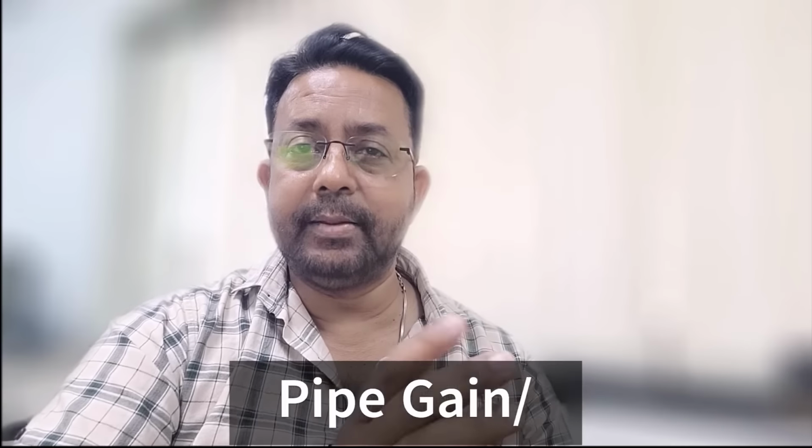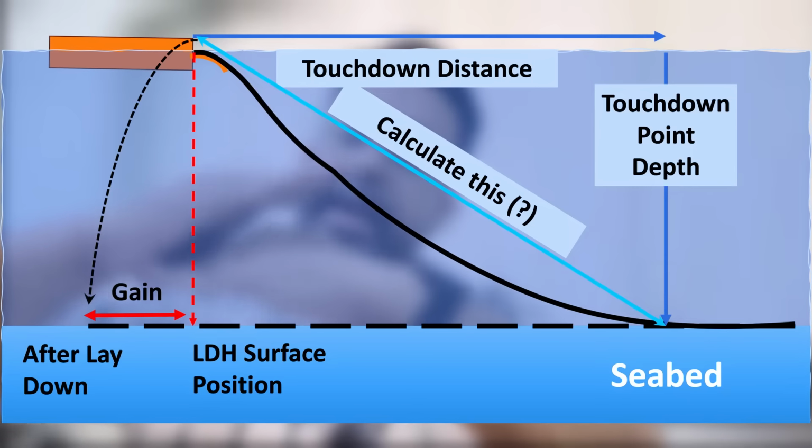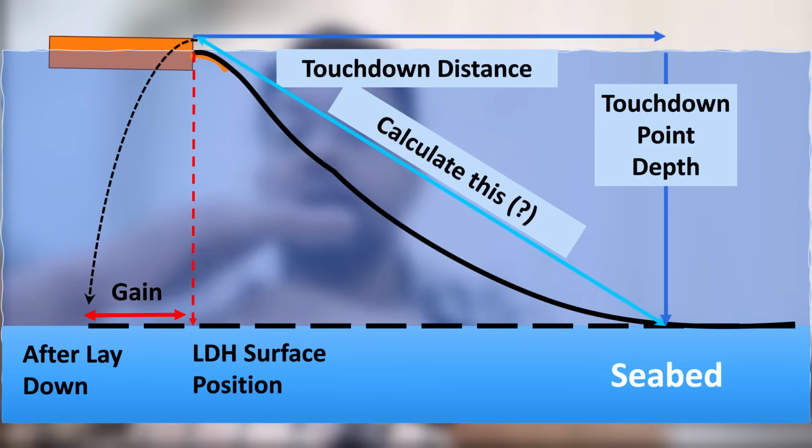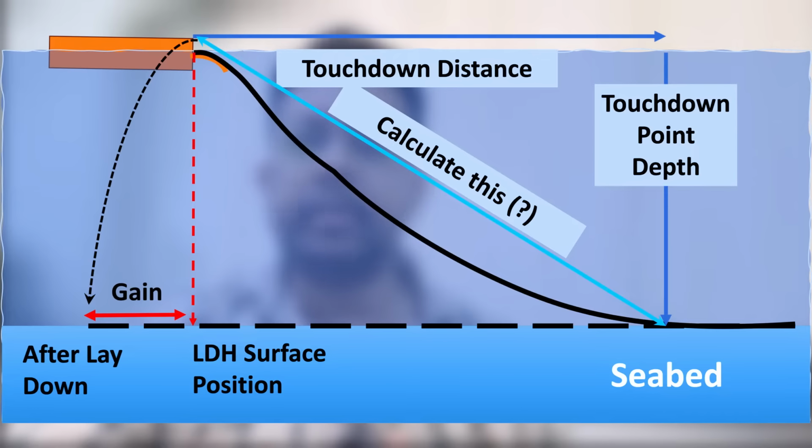Here you need one more data from the field engineer, and that is gain or flop forward. See, the end of the pipeline is on the barge, which is say about 80 meters above the seabed. So when it falls down, it gains a few meters from the position calculated at the beach stall. You can do a simple Pythagoras calculation, but that won't be that accurate as you don't have the information about the catenary or how much the pipeline is sagging.